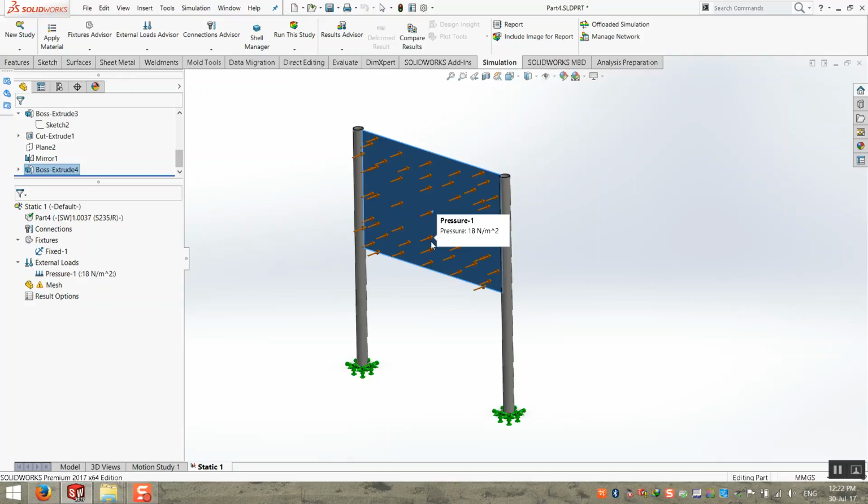Convert this surface to a million points, and apply the force equation on each point of this million points. After that, these points will get a deformation, and you see finally the shape like that. Now in complicated shapes you may have this error. This means that you need to make this mesh step manually.